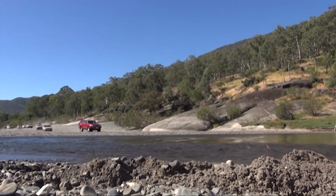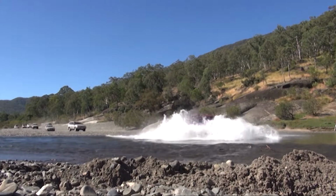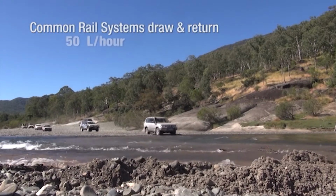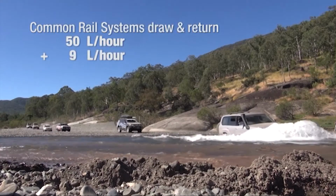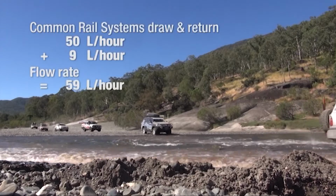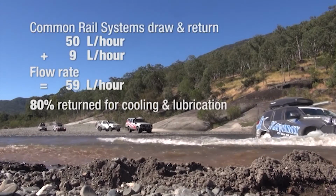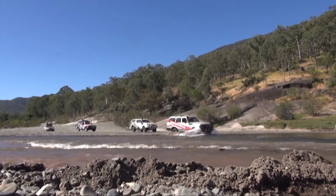How do we stop our vehicle getting water in the fuel system? We have really high flow rates. Common rail draws from the tank and returns in the vicinity of 40, 50 litres an hour, and another 8, 9 litres which is used. So we have a flow rate of 50, 60 litres an hour through the system. 80% of this is going back for cooling and lubrication of the components. So when we get water in it, it quite rapidly is carried through the system.